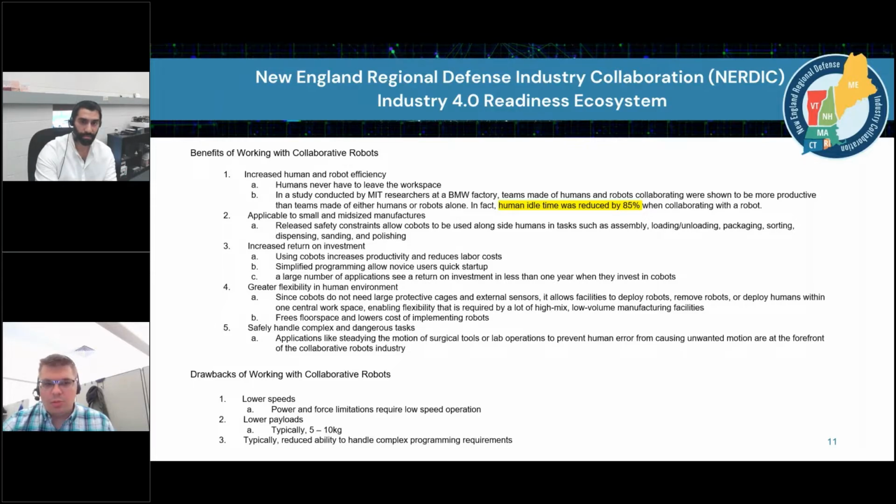Usually the robots may be able to do it, but it becomes very cumbersome to program compared to an industrial robot. Again, this isn't typically an issue when you're working with standard pick and place type operations, some palletizing operations, loading and unloading a machine. It's not typically a big deal. It can cause a problem when you're doing the more complex motion profiles like deburring parts or some stuff like that. But then it really comes down to the particular cobot in question.